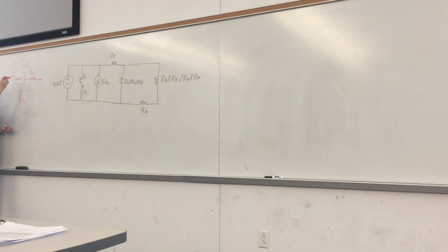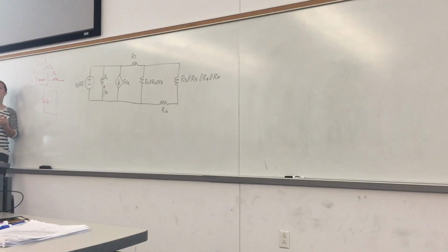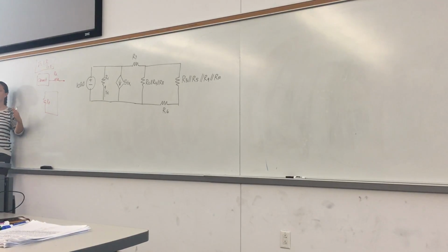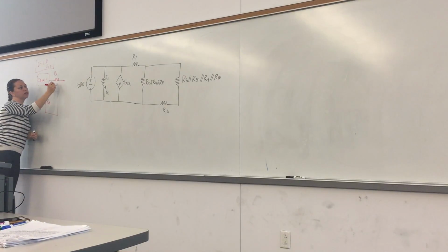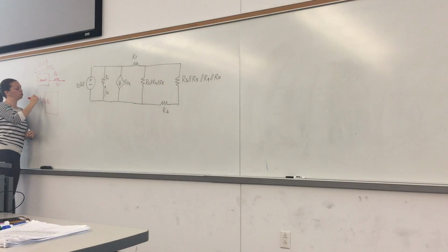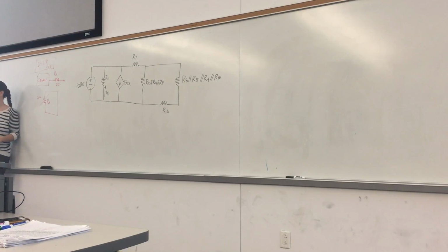So anytime current or voltage becomes 0, the other one also becomes 0, right? So in those cases, we're going to be ignoring those resistors. In a given question, you can simply say that that's open circuit or that's short circuit, and then you can just cross it out. We will know that you're ignoring that resistor because it's shorted or because it's open circuit.